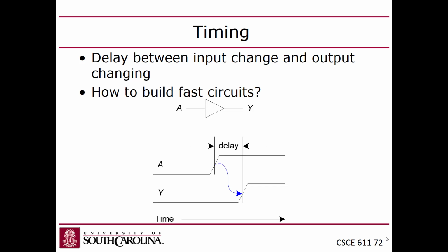Now, there's also a time, by the way, once you've charged the capacitor of a gate, it takes the charge carriers time to traverse the channel. It takes time for that, too. No one talks about that anymore, though. Why not? Because that was one of the big advantages of Moore's Law. It was shrinking the transistors down, shrinking the channel down. That sped them up because the charge could get from the source to the drain faster, because that channel was getting smaller. But anyway, for all of those reasons, gates have a delay.